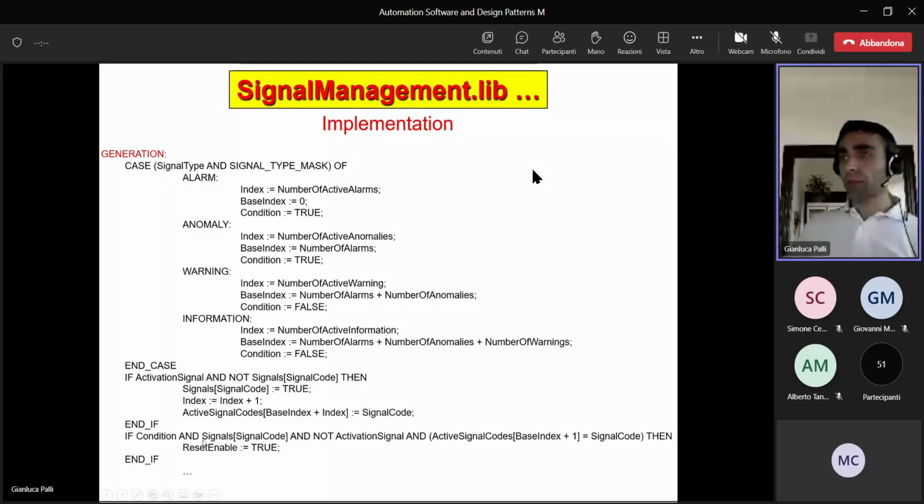Then we check in the second if condition if the conditions for the specific signal to be reset are satisfied in order to enable the reset. So we have to check that this is a resettable signal, so an alarm or an anomaly, the fact that it's active, the fact that the activation signal is not present anymore, and the fact that this is the signal code that we have at the top of the list of active signals.